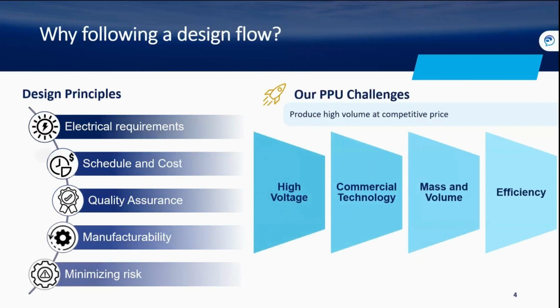For example, the high voltage requirements are super demanding in both projects, and this means added complexity. For instance, our positive high voltage module has to provide up to 1.5 kilovolts to the thruster screen grid. So as you can imagine, when designing, this means adding a lot of restrictions, for example, with PCBs or testing assemblies or validating components. So yeah, this is quite a restrictive requirement.